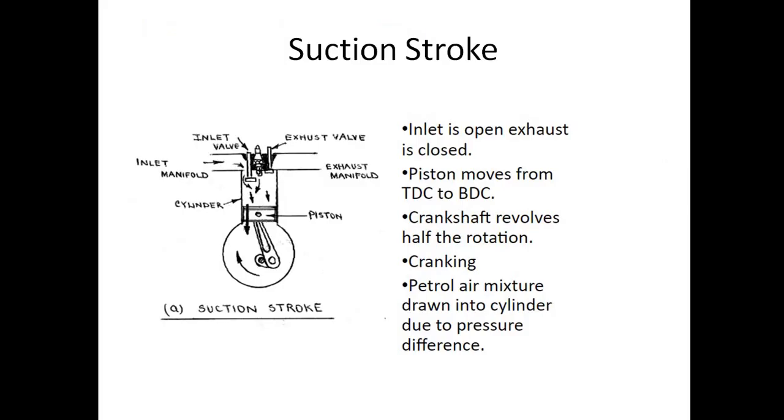The same thing is given over here. This is the suction stroke. Here we have opened the inlet valve. As we open the inlet valve and the piston moves from TDC to BDC, suction will be created, and through the intake system or inlet manifold, the fuel air mixture will come inside the cylinder. During this, the valve will remain open.